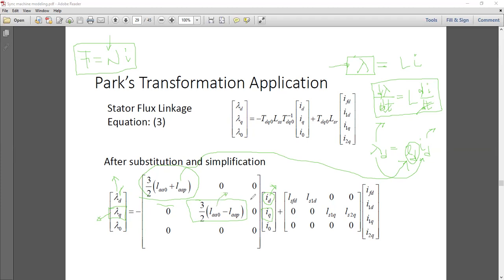This is another benefit, as I mentioned in the last class, of keeping the d and q axes 90 degrees apart, assuming they are hypothetically placed 90 degrees apart. So these are additional advantages. You are getting many zeros. While calculating numeric values for lambda d, lambda q, etc., you only have to think about this term. There is no linkage between d-axis and q-axis terms.